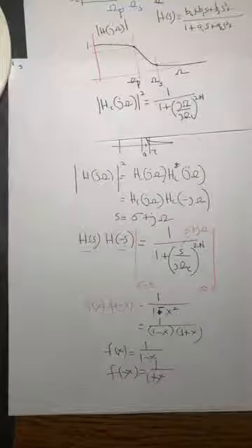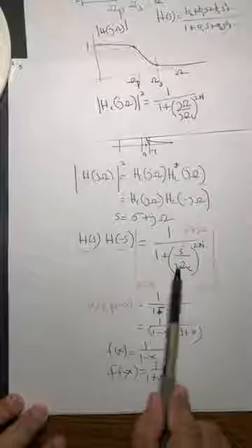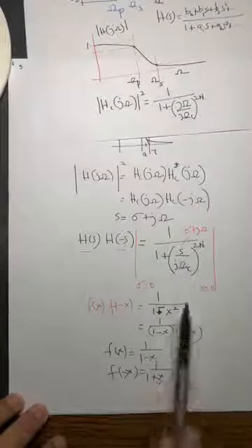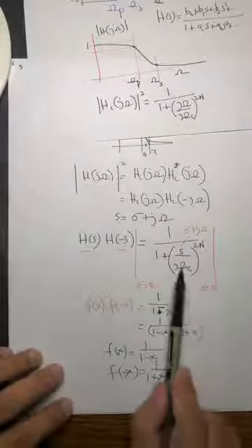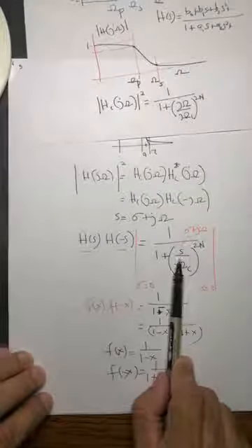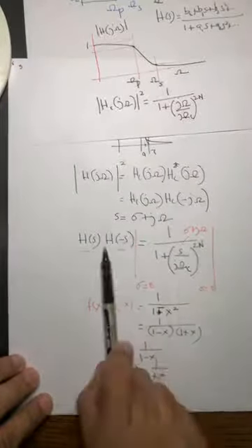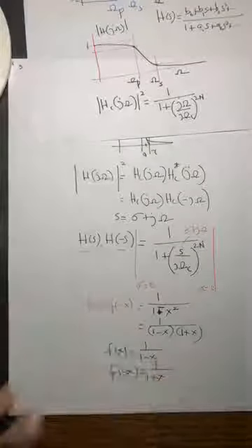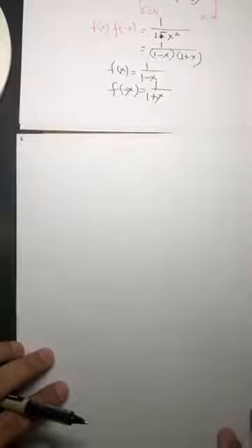Okay, so you have to come up with something like this where you first expand this function into its factors, and then split them into two parts. Also, he must be thinking about how to expand this into factors, give half of them to H of s and the rest half of them to H of minus s in a way that this relationship is not violated. So here comes the third part of it. So slowly but surely he's moving towards a solution, a discovery.